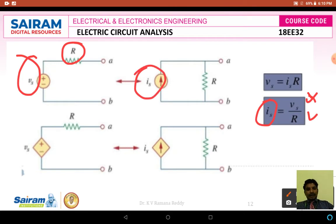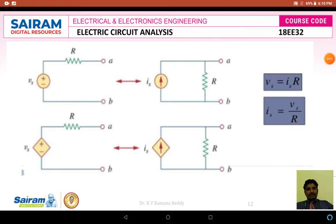And what about the internal resistance of the current source? The internal resistance of the current source is also equal to the internal resistance of the voltage source. But the way we place that internal resistance differs for the voltage source and the current source.